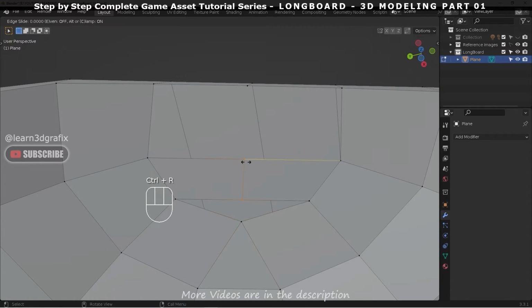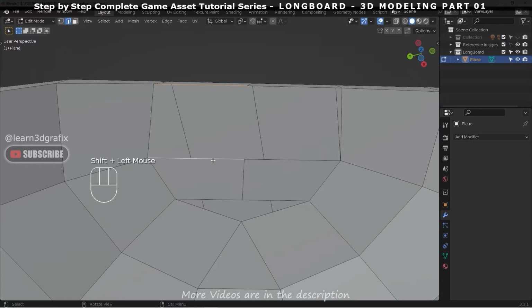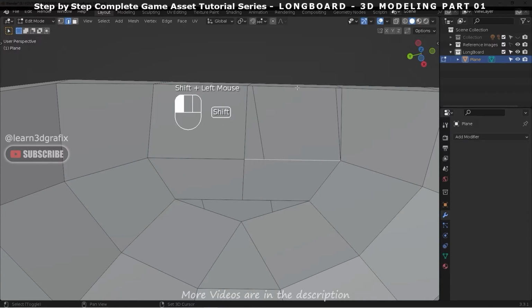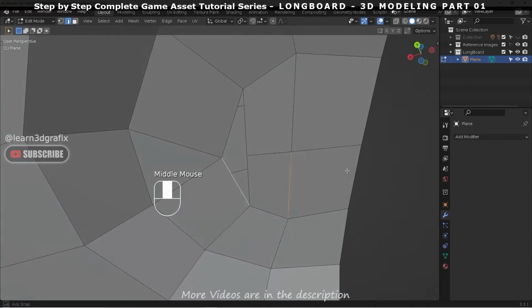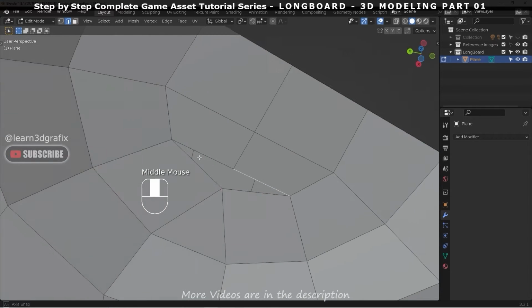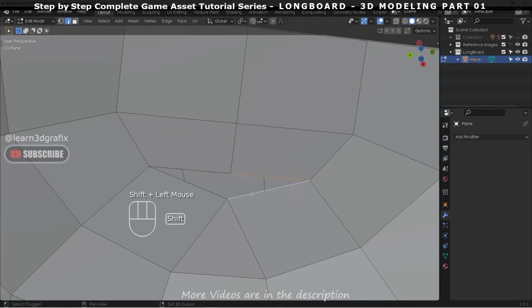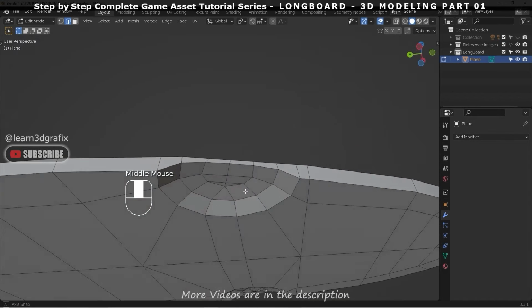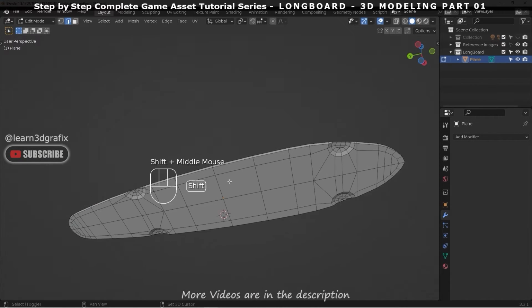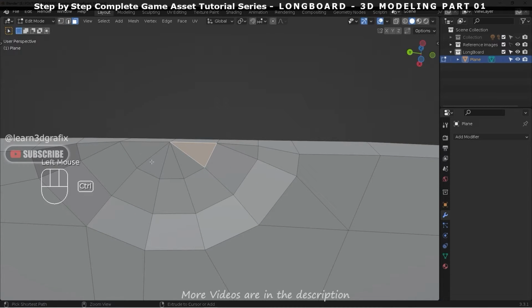Press Ctrl R to insert an edge. Now select these two edges and press F to fill, and these two edges and press F. Now select this edge and this edge and press F. Let's move on to the other side of the deck. Let's repeat the process here.